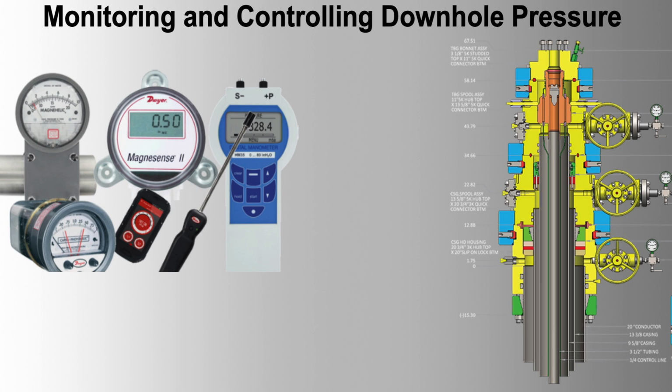Example issue 1. Instrument failure due to high temperature and pressure. Problem. Standard pressure gauges failing at high temperatures and pressures. Solution. Use quartz pressure gauges designed for high temperature and high pressure environments. These gauges provide reliable performance and accurate measurements under extreme conditions.